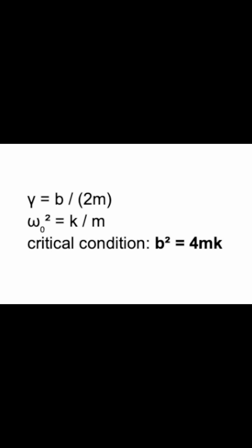We rearranged this and solved for the critical mass, and that gave us a value of around 0.670 kilograms. That was the mass needed to achieve critical damping with the damping coefficient and spring constant we calculated. And then in our results, we observed that the system motion resembled a critically damped response. It returned to equilibrium without visible oscillation and in a relatively short time, which matched our expectations based on theory.